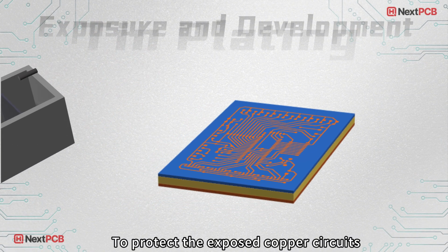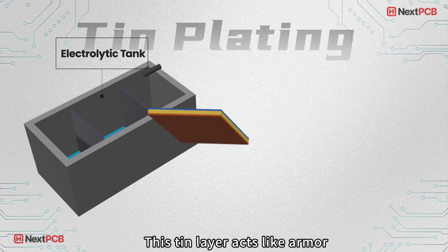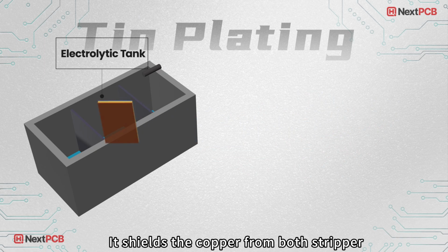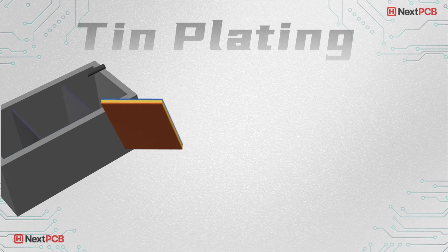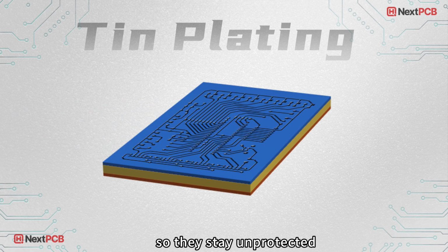To protect the exposed copper circuits, we electroplate them with tin. This tin layer acts like armor. It shields the copper from both stripper and etcher chemicals. The areas still covered by film won't get plated, so they stay unprotected.